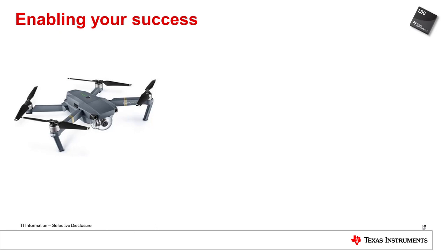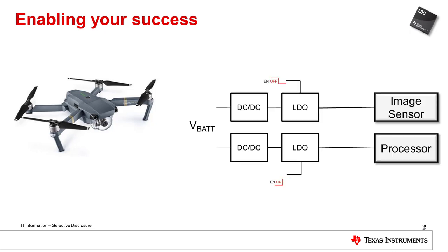An enable or shutdown pin is another simple solution if you're designing to conserve battery life. Smartwatches, fitness trackers, phones, and even drones can employ the solution for a battery boost. Drones, out of all the consumer electronics that were mentioned, spend very little time in standby mode because they're usually only idle pre or post flight. However, you can still save battery life by shutting down LDOs attached to those modules not needed for flight. A good example for these modules is the image sensor, as this is only needed when the user wants to record videos or take photos.